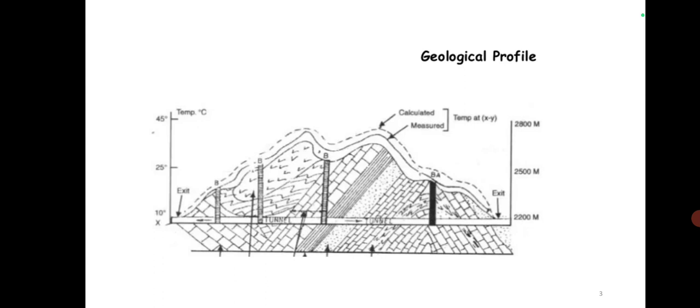Okay. So slate and phyllite with a high degree of cleavage. Slate and phyllite without cleavage, we can consider an ideal condition, whereas slate and phyllite with a high degree of cleavage, or decomposed varieties of igneous rock which have undergone weathering and decomposition, are all categorized as soft rocks. The cost of excavation is low, because it is easy to bore or drill through these soft rocks. But since these rocks are not self-supporting, permanent and temporary lining is required. So this lining adds to the cost.